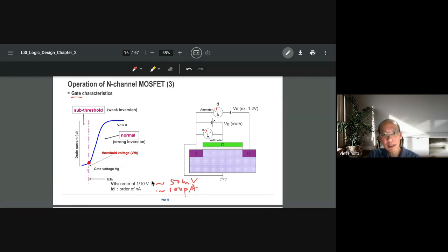As I said, because they reduce the voltage, you have less leakage. It contradicts what I just said, that we have to dope more, right? So that's going in the opposite way here. One is you have to dope more impurity so that we can get high current.